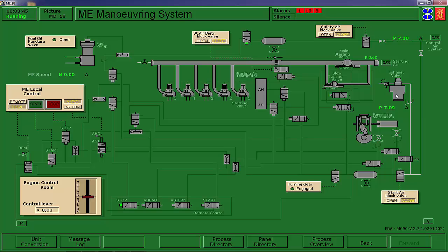Then when the exhaust valve actuator starts moving up, the oil in the hydraulic push rod is locked and none of it will flow out, so all of it goes to pushing on a piston that opens the exhaust valves.